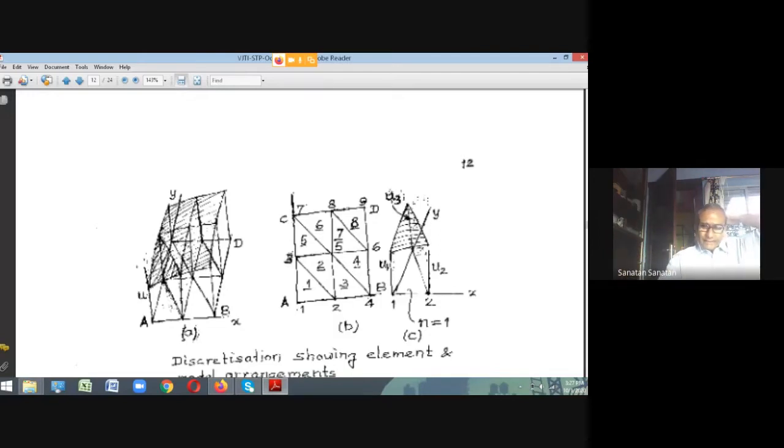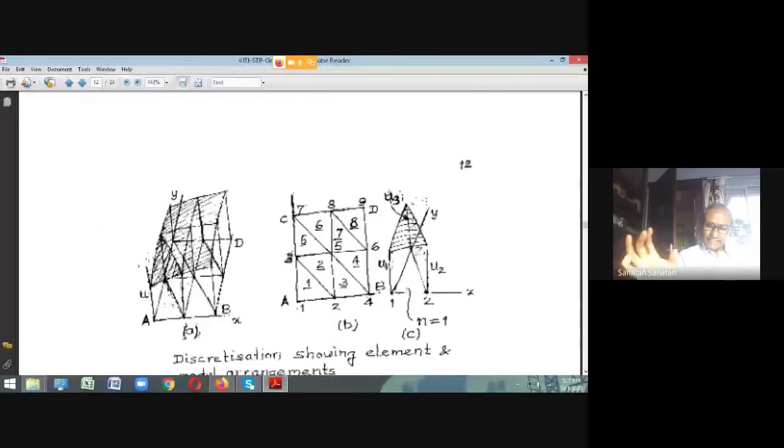And if you now shrink the size of this element, make it smaller and smaller, it will become a small patch of that surface. It will look like a triangular tile. It's a flat tile. Is that clear to everybody? As I shrink the size of this element A23, the surface size will become small and it will look like a flat tile. It will not be doubly curved. That size is so very small, it will look like a flat tile.